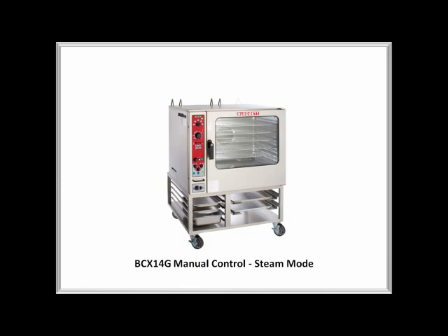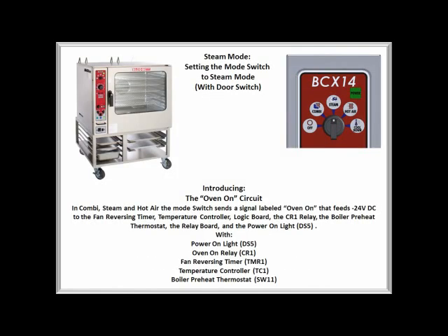Now we will review the steam mode. When the mode switch is turned to steam, combi, or hot air, the mode switch sends 24-volt DC return to many components in the unit, and we call the output the oven on signal.